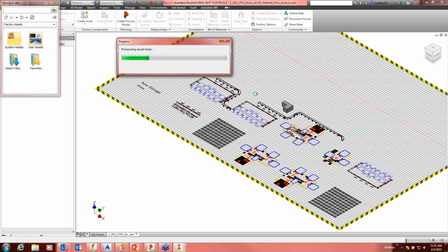So while this finishes up, we're making our last couple of turns here. You'll just see those drop into place. And when it finishes generating this, you'll see underneath the polyline path that I had drawn in. And another great thing is that when I go back to my 2D model, you're going to see the actual conveyor there, not that bold polyline. So it's going to finish up here. We're going to start to see the 2D show up underneath.